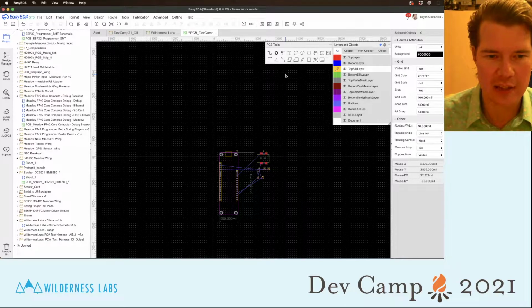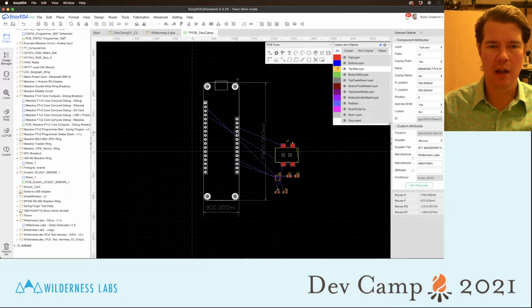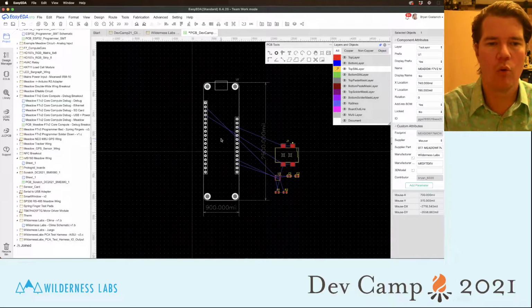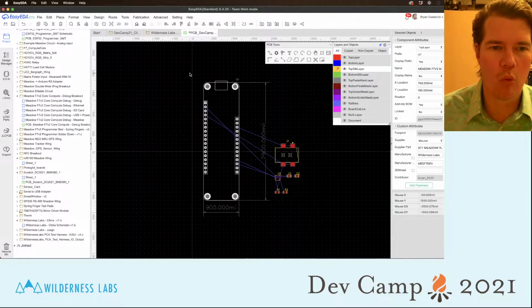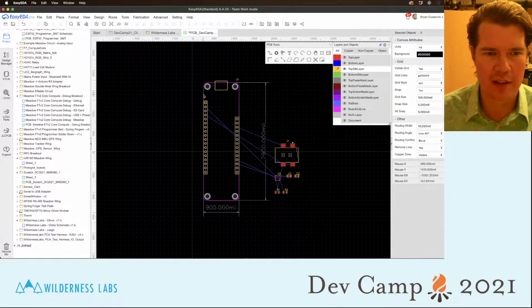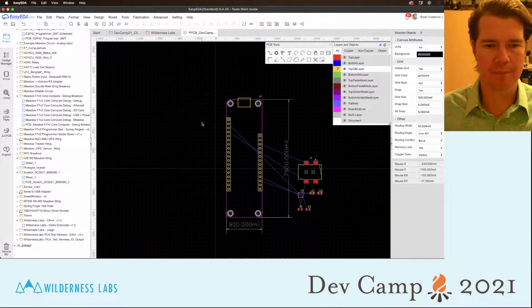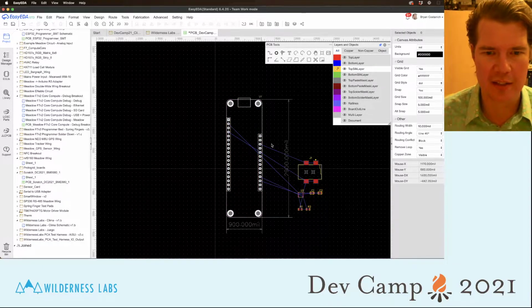And I'm going to delete that because we have started with a Meadow wing. And when we imported the Meadow through-hole wing symbol, it automatically came with this footprint, which already has the wing outline. So it's a nice shortcut. So we're going to use that as the outline.